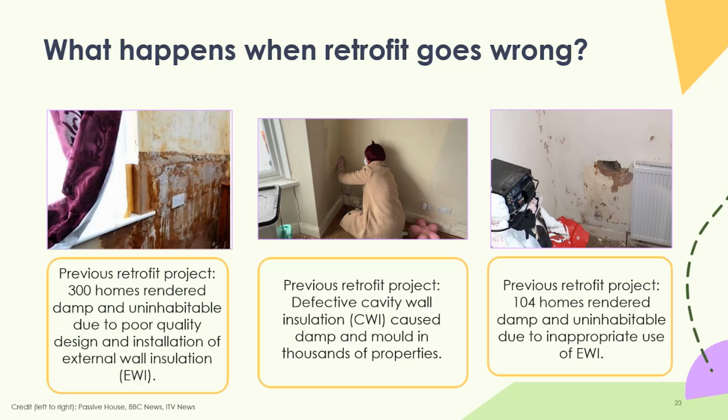Well, it's only one photo. I can't get the full diagnosis, but clearly the EWI has been installed improperly, and there's been water that's either come down the back of it, maybe it's not been capped off properly, or the roof line not extended, and that wall has got damp. And then you're seeing a lot of clear water damage as that wall has become saturated with water. There's probably some fungus growing on there and all sorts of nasty stuff.